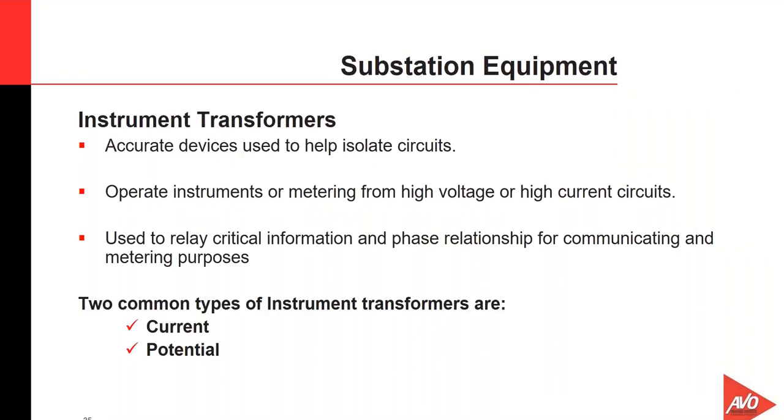So let's get into a little bit about CTs and PTs. A current transformer is a type of transformer that is used to measure AC current. Okay, it produces an alternating current which is proportional. Okay, proportional meaning that there's a ratio. Usually that ratio is going to be a 5-to-1 ratio. All right, it's going to be proportional to that current on its primary.